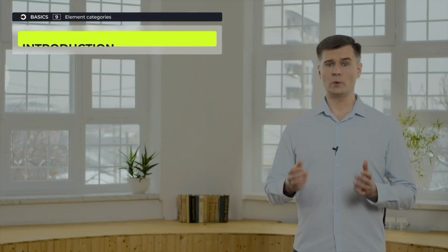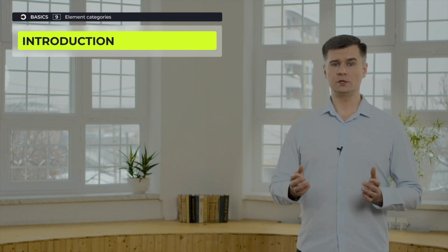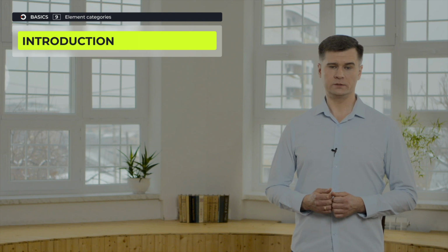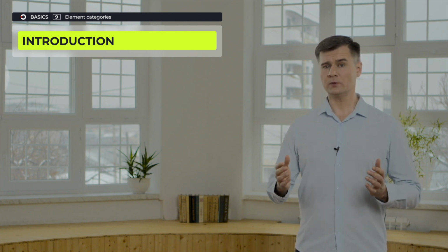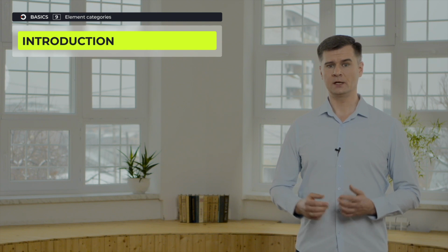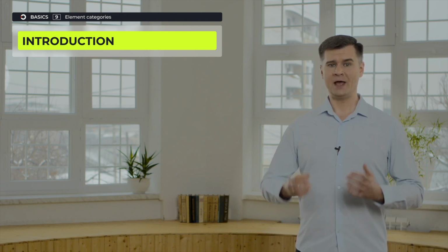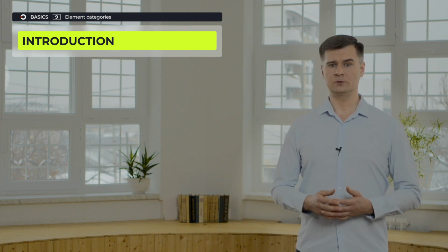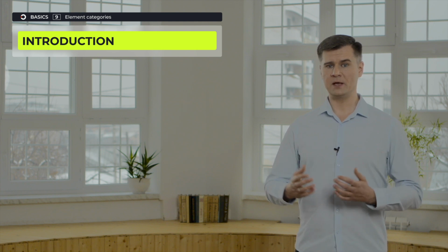elements. It is quite a common situation that you need to sort out elements of a particular type, say all walls, for instance. And of course, we are able to iterate through all the elements in the container, verify their types, and pick up only the ones we need. But that doesn't seem to be an efficient solution. And indeed, there is a better way.